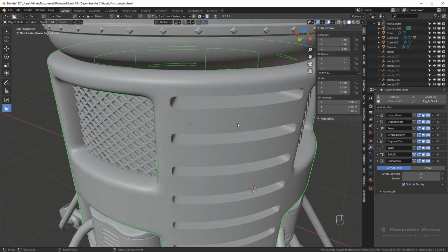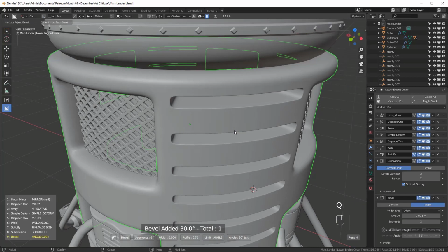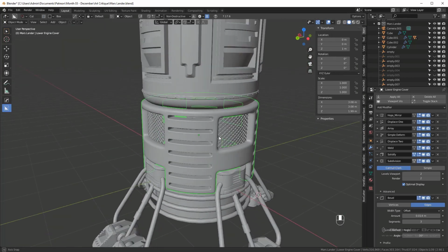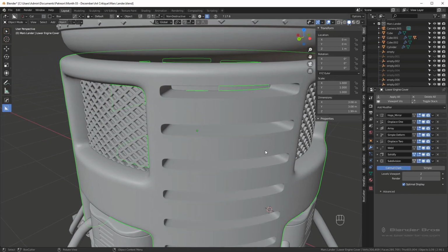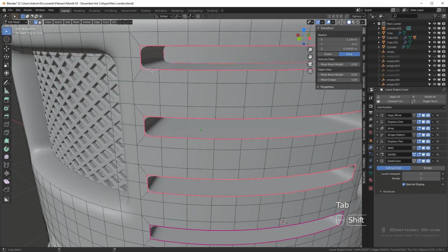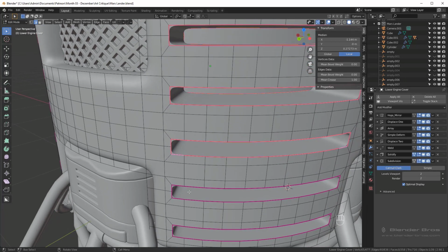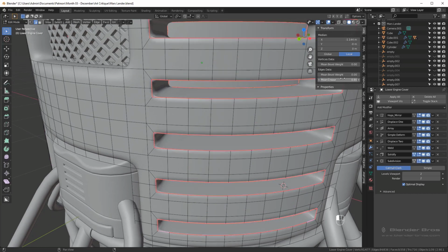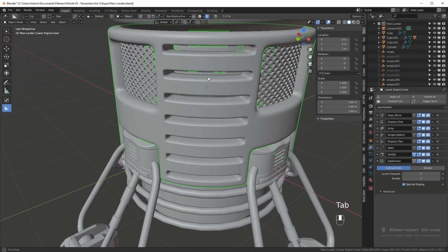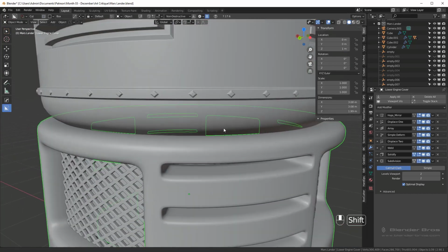So what you could do is come in here and add on, I don't know if this is going to collapse because of how heavy it is, but you could combine the crease with a small bevel like this, but I don't think it's really necessary when you could simply hold off on your creasing, right? You don't really need a full level of creasing. Just go in here, Alt-Shift click everything, and maybe give this mean crease like 0.8. That's actually probably too low. We could disable auto smooth or just go for like 0.7, 0.5. There we go. Yeah, go for something lower like 0.5. It'll have the same effect as the bevel.